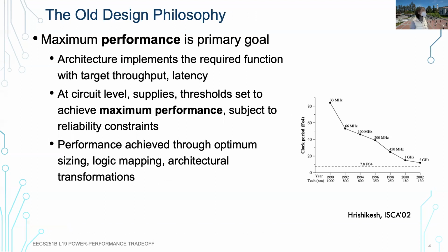I was digging through some performance papers from around 2000, and I have an IEEE paper there. Back then, a lot of the discussion was about how deep we could go with our processor pipeline. We really wanted to go super deep, with very little computation in each stage, so that we could clock at a higher frequency, because each stage is so short.